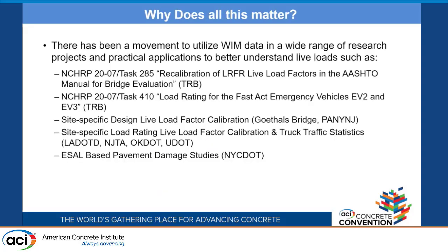So again, why does all this matter? There have been multiple projects out there from NCHRP: recalibration of the LRFR live load factors in the AASHTO Manual for Bridge Evaluation, and NCHRP 2007, load rating for the FAST Act emergency vehicles, EV2 and EV3. So those are two national-level projects looking at recalibrating that design load.